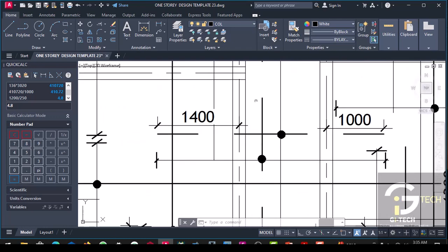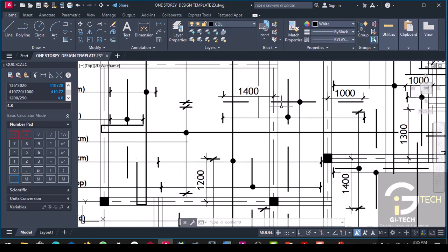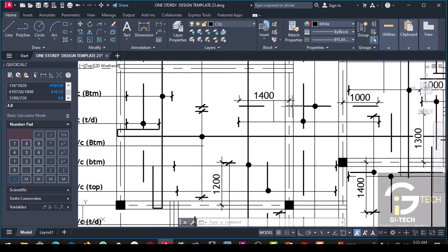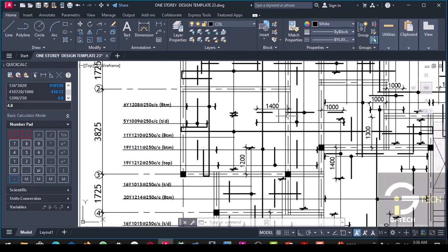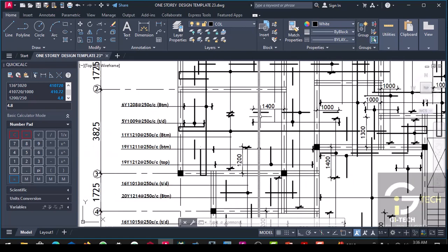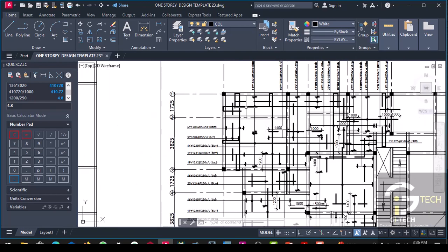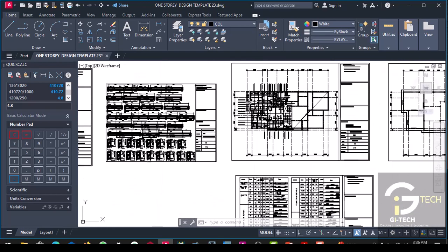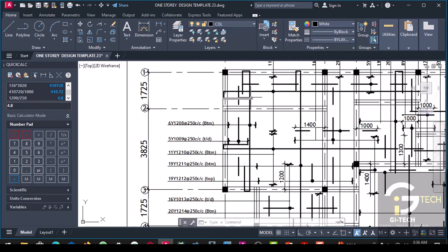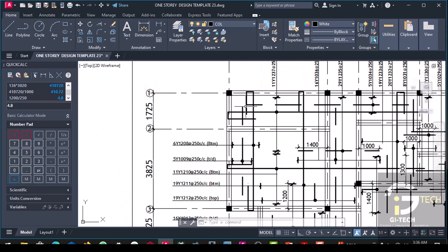Now for the interior support, for you to get the length of this top reinforcement, you have to multiply this adjacent span with 0.3. So that is the rule. But practically, sometimes we don't really follow that, because if we follow that, sometimes we might waste the reinforcement.